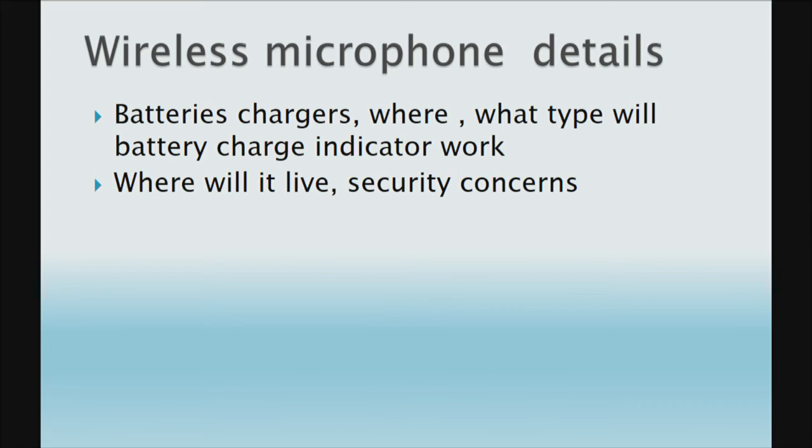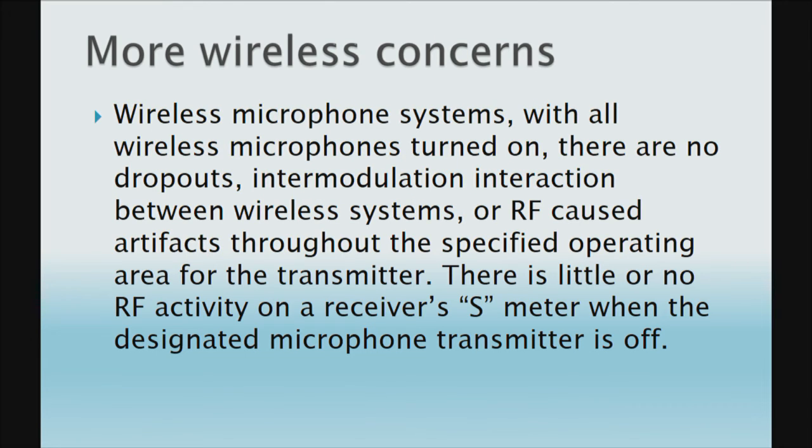You know, let's say you're speccing batteries. A lot of nice receivers, you can go in and change it from alkaline to nickel metal hydride or something like that. But make sure the model you spec can work with the batteries that you plan on using. And security, you know, a lot of us have open campuses. What do you plan on doing for security with the microphones?